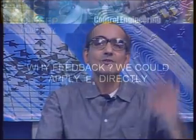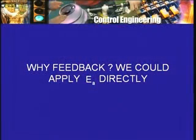But to come back to what I was talking about, we don't really need feedback. I don't really need that tacho generator output and so on, because directly 1500 RPM requires 230 volts. 230 volts is produced by, say, 1 ampere of field current, and that 1 ampere of field current is obtained by some voltage of 20 volts somewhere. So 20 volts produces 1500 RPM. I want a different speed, different armature voltage, different field current, therefore a different voltage somewhere else. Why do I need feedback? Why do I need a tacho generator? In fact, I don't.